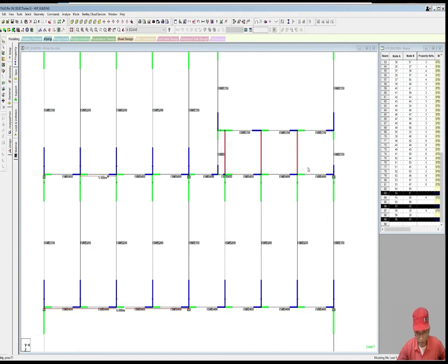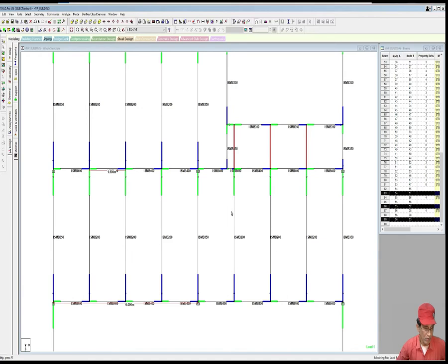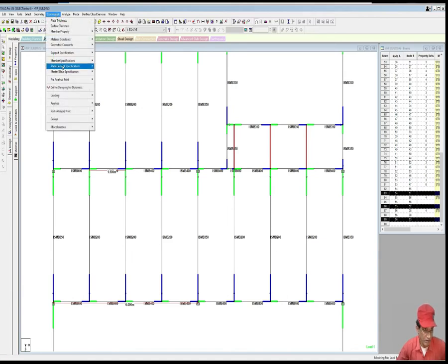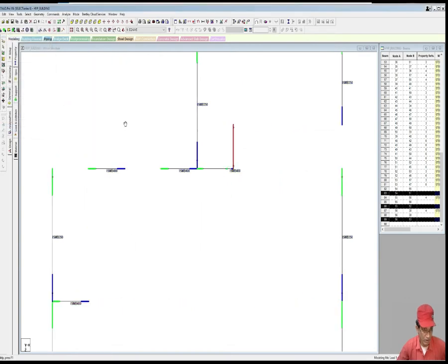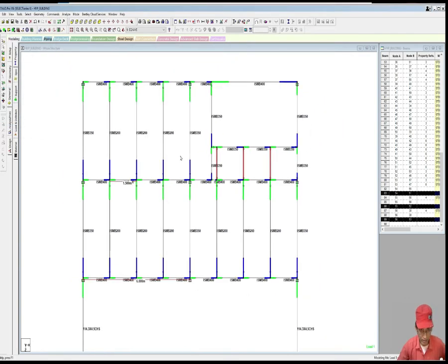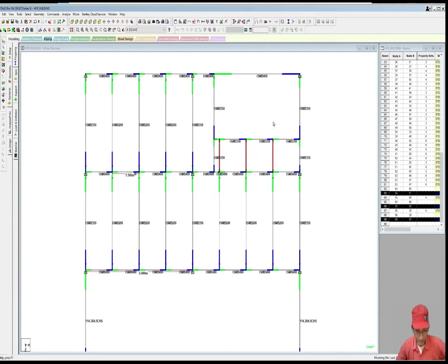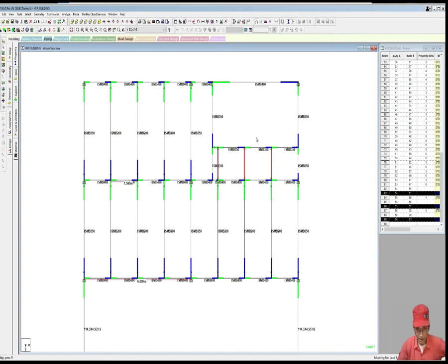So these are also joists, so I have to assign releases to this. So go to command, member restriction, releases, start MY MZ, end MY MZ. With this, our framing part of mezzanine is complete. Now we shall try to model the stringers of the staircase.